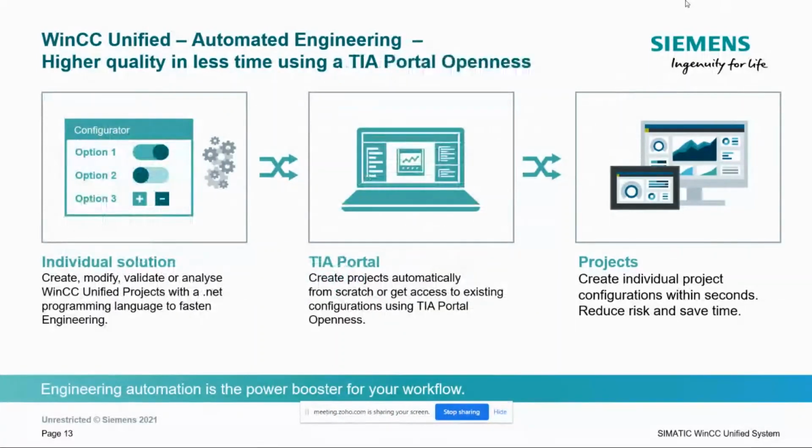Okay, so I'm pretty sure you guys have heard of Openness, the TIA Portal. You can also bring in some of your HMI and bring in your function blocks, your data blocks, your whole program, and you have to do some coding in like .NET and then also Excel. You can use Excel, and so basically, once you do this and you compile everything, it'll go right into the portal and then build your program for you and build your HMIs for you.